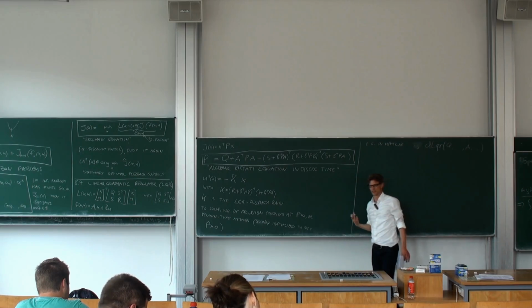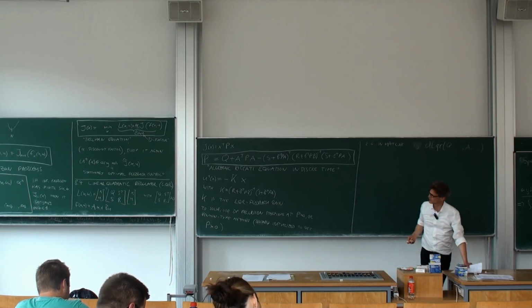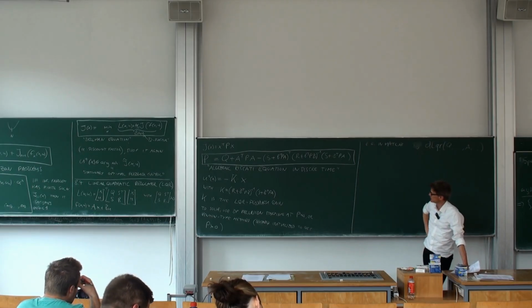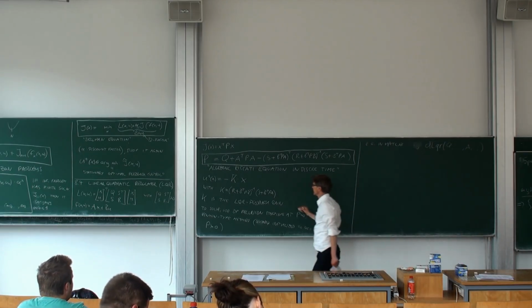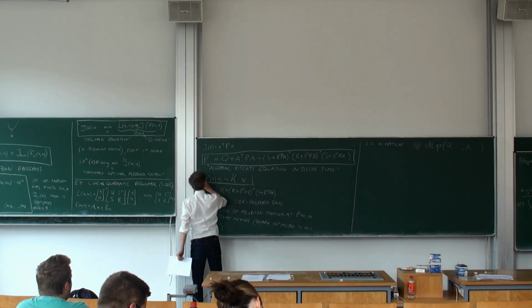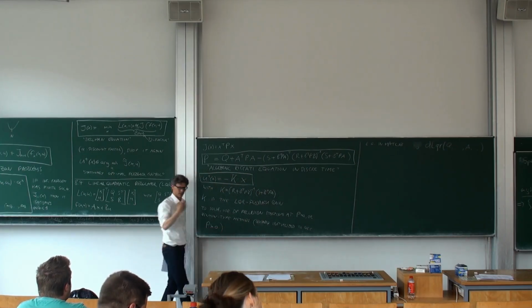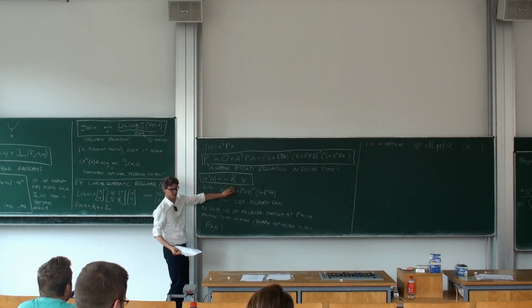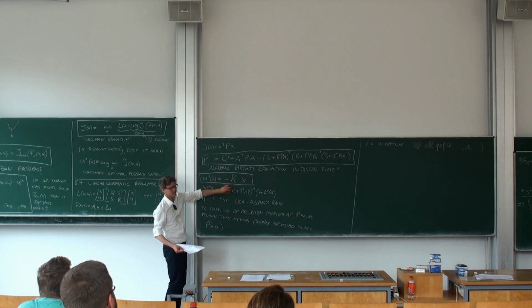And the beauty of it, and that's also the reason why it's so widely used, is that at the end you get this optimal feedback control, and it's just a matrix multiplication. The only thing you really need to remember when you want to implement it on a real system is this matrix K. You don't care how it was computed, via this matrix P and this complicated expression.